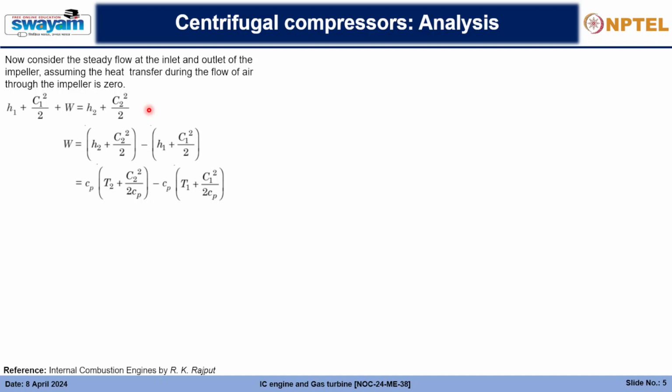So that is work done on the system. And you will remember in thermodynamic analysis, we take work done on the system to be negative. So that's why it comes to this side and it becomes positive here. And there's no heat transfer, so the heat generation or heat transfer will be 0 out here.